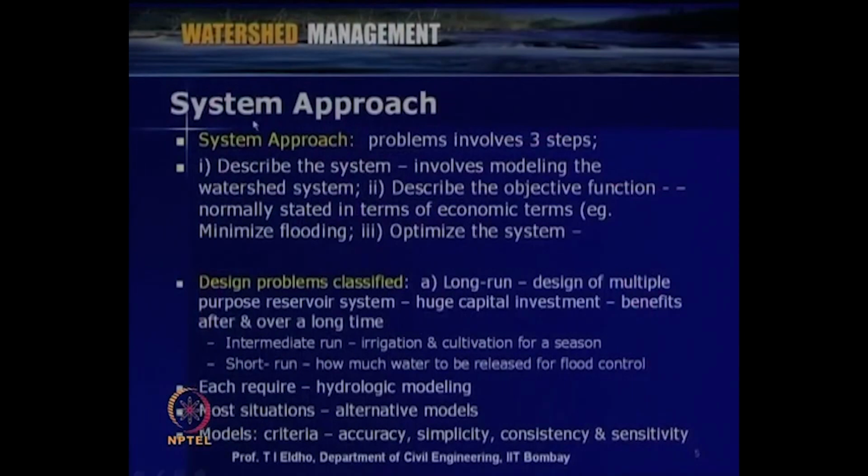Most of the time we will be looking at the watershed simulation using a model with a system approach. In the system approach, if water related problems are concerned, we can use various conservation principles like conservation of mass, conservation of momentum, conservation of energy, etc. If you consider conservation of mass, then inflow minus outflow is equal to rate of change of storage. Like that, we can develop a system of equations for the given watershed area by using a system approach. So, the system approach is generally used for watershed modeling.